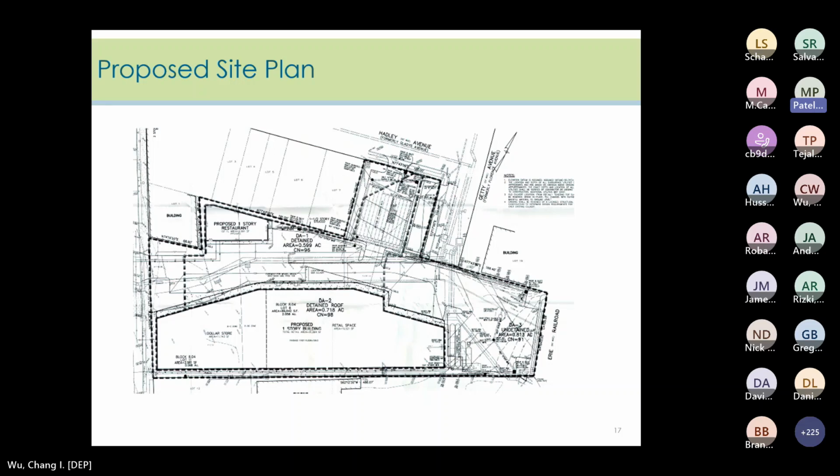One criteria is that the basin will need pretreatment of runoff to 80% TSS removal rate, but we didn't see one available to us with the plans for this project. Additionally, the roof runoff was commingled with the runoff from the parking lot, so the commingled runoff would have to be pretreated to 80%. If they separate the roof runoff and direct it directly into the subsurface infiltration basin, it may just need a leaf screen to pre-treat the roof runoff. These are just some design criteria you would need to consider.